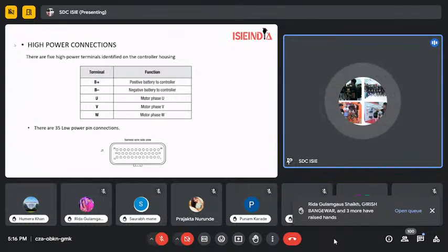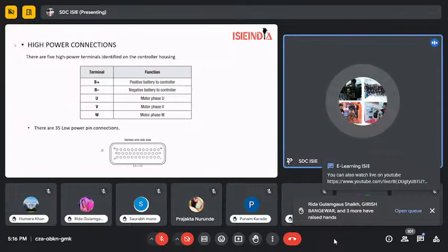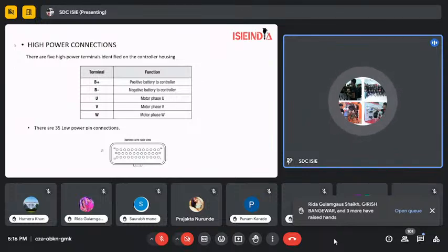Along with that, we will find that we have 35 pins and each pin has a different function. In every controller of the Curtis brand, 1232, 1234, you will find this type of architecture, with 35 pins that communicate for features like the key switch, auxiliary connection, temperature sensor, throttle, the wiper of the high potential, encoder wire channel, battery system, CAN communication, high CAN, and low CAN.